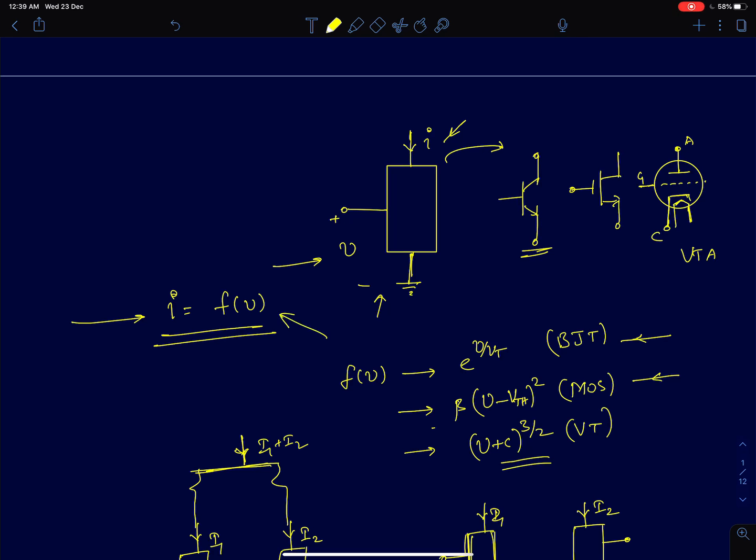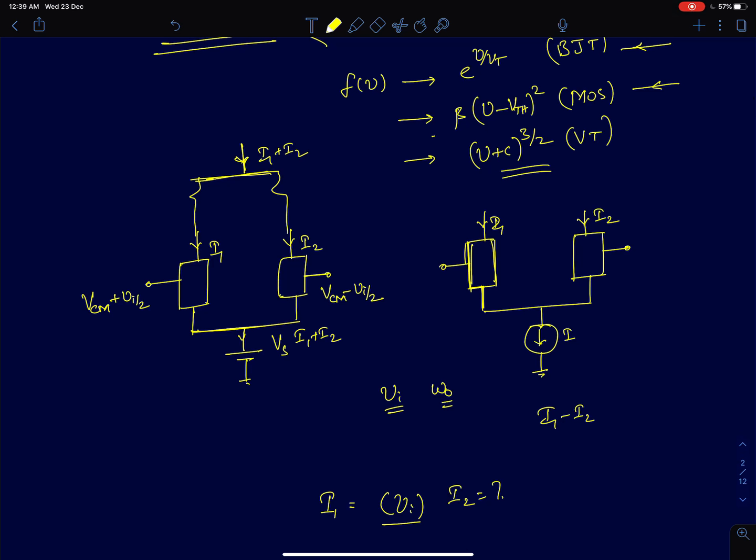Now let's start with a constant voltage biased differential amplifier. What we are essentially going to do is apply a sinusoidal input here, Vi, of frequency omega naught, and then study the frequency content present in I1 and I2, and the frequency content present in the supply current, which is nothing but the sum of the two currents.